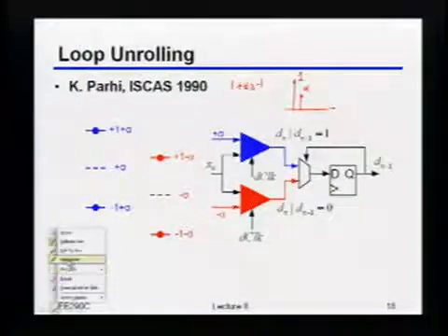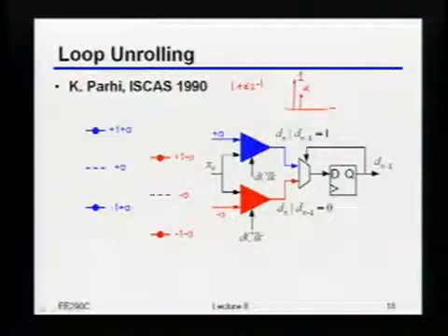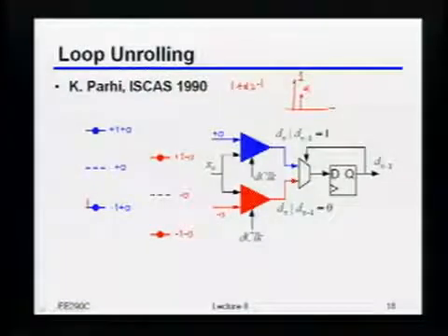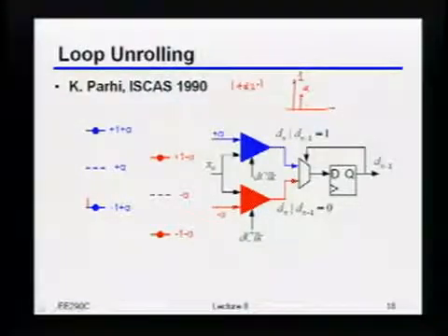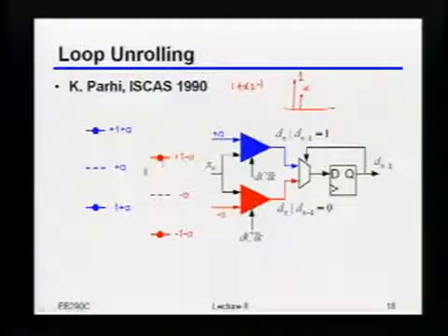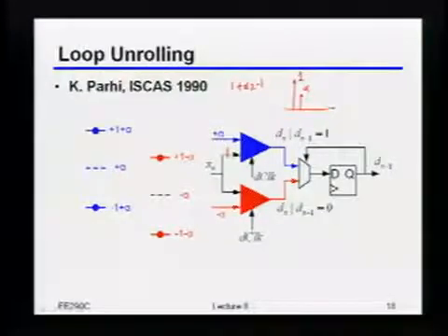So the visual mapping that you're supposed to get from this picture here is that if the previous bit was a 1, that's like saying that what I'm sending this bit will be shifted up by plus alpha, right? And if the previous bit was a 0, then what I'm sending this bit will be shifted down by minus alpha, right? So it should hopefully be clear that if you take these two comparators, one where you've shifted the threshold up by plus alpha, then that's as if the previous bit was a 1. And if I shift it down by minus alpha, then that should be the correct slicing point if my previous bit was a 0. Okay?